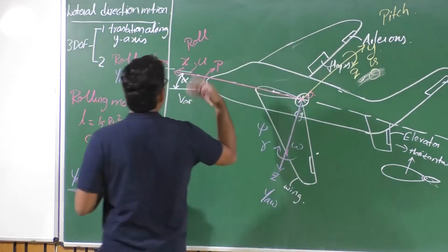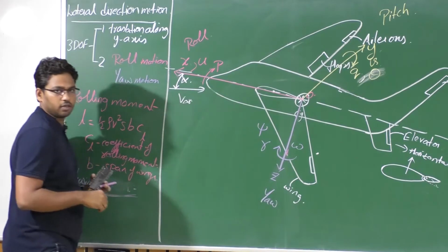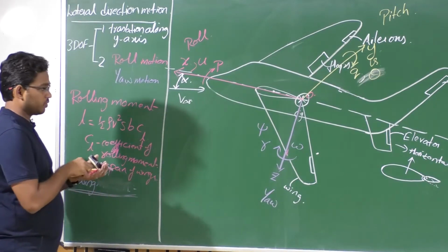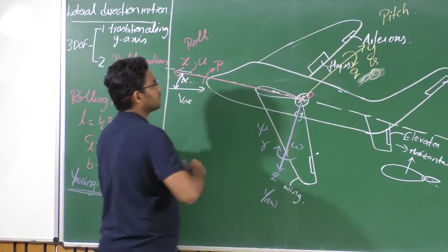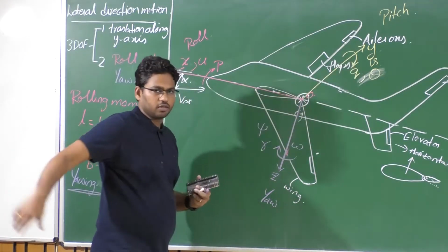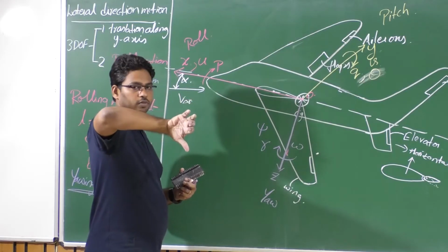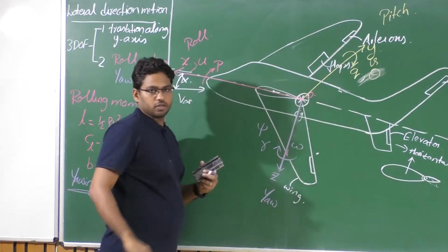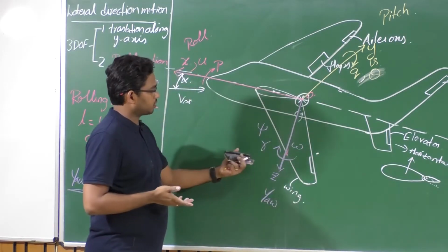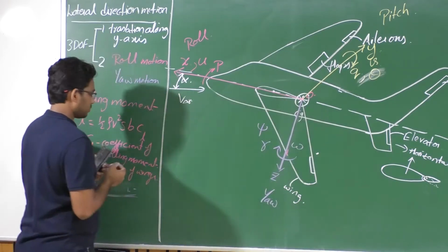Under no other rotation, psi dot is equal to r. That is single plane rotation. The positive yaw is given by the right wing going back. If you stretch your thumb along the positive z-axis, the curl of your fingers will give you the positive rotation, where the right wing going back corresponds to a positive yawing moment.